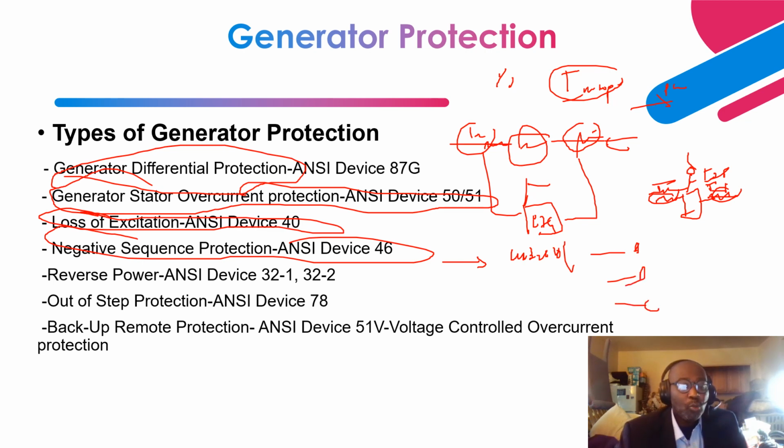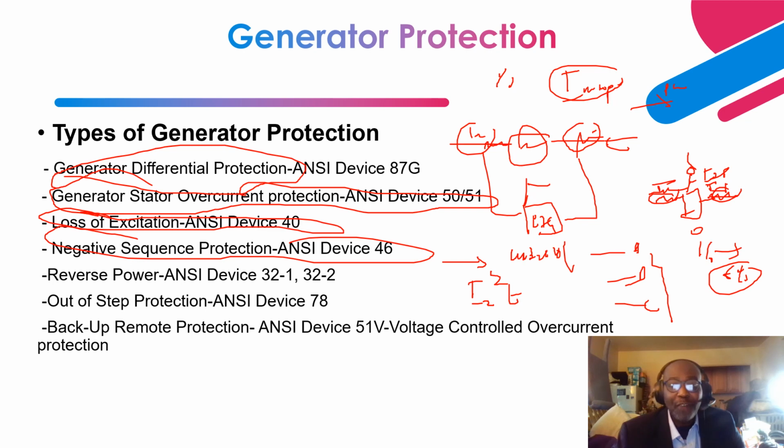What this protection element does is it protects the generator based on an unbalanced difference in voltage between each phase, right? For each 1% unbalanced voltage, it translates into 6% negative sequence current. So this protection element works based on the negative sequence current squared times an allowable time duration that the manufacturer will provide to you.